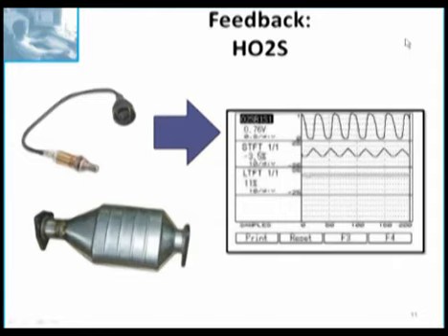So another thing that will happen with an O2 sensor is the heater goes bad. And that's a pretty quick test because you run the engine at 2,000 RPM until the oxygen sensor gets hot and it's responding well. And if it responds well by heating it, and then it starts to slow down when you go to idle, that's a pretty good clue that you've got a heater issue.